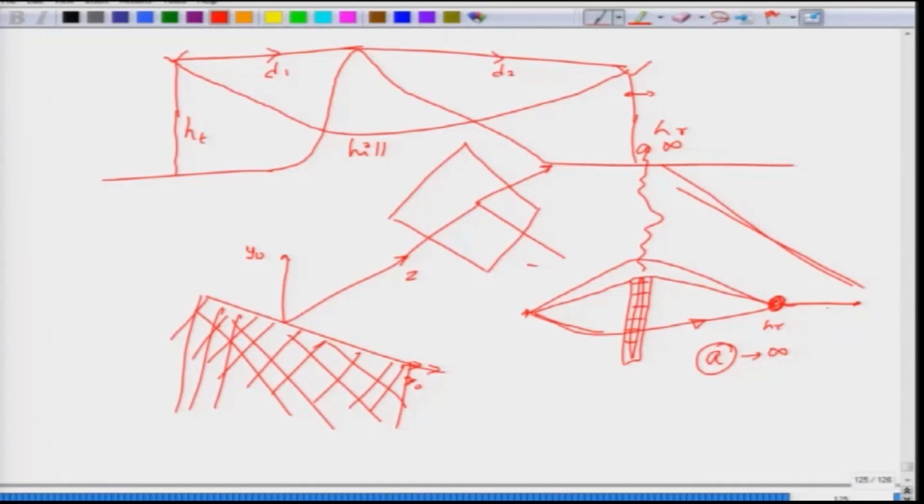Okay. So, what we want to understand is what happens as I reduce or increase the antenna height, and maybe I do it at different distances away from the building. Will my reception improve or reduce? What you will see is that as the height is increased or decreased, as you move deeper into the shadow region or come out of the shadow region, the total electric field that is received, or the intensity or the power of the field, will oscillate in a certain manner.